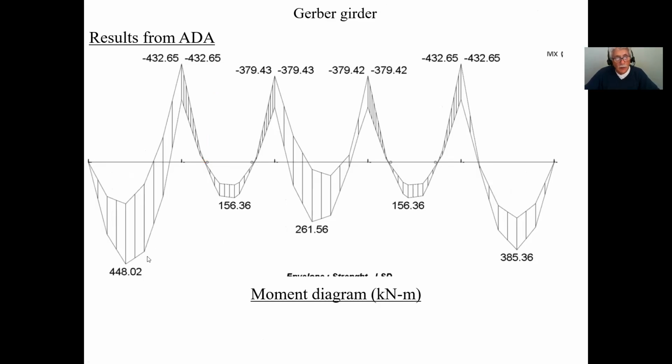Okay, now these are my moments. Now guys, very simple. Here's my drop-in beam, like this. It only has a positive moment. And of course, it's laterally supported at every 2 meters. So now I can go and size that because I have my LU of 2 meters, 2000 millimeters. I have my MF of 150.36, and I have my VF value.